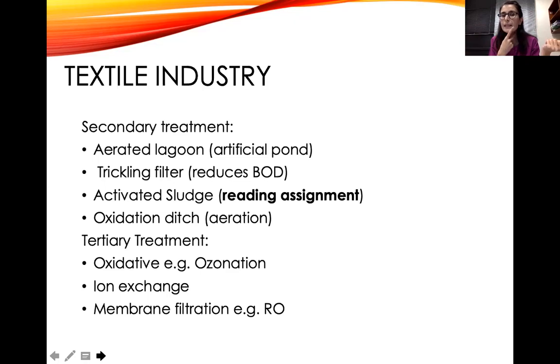They had basically installed a microfiltration, not reverse osmosis, a microfiltration for a membrane bioreactor. But because the strength of the wastewater was really high, it had very high COD, very high BOD, and all kinds of things suspended in there. They were continuously using it. And what happened was, within a year, the membrane clogged, or the pores clogged. And the administration had an issue that it shouldn't clog in a year because they were told that the membrane will work for 10 years.